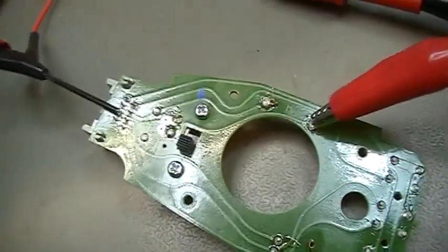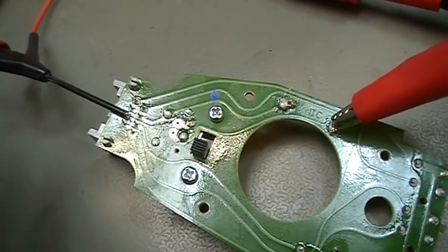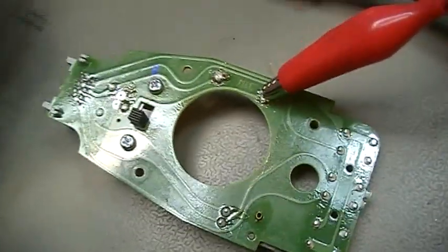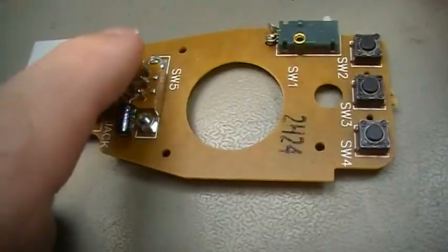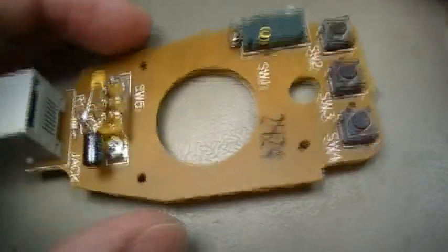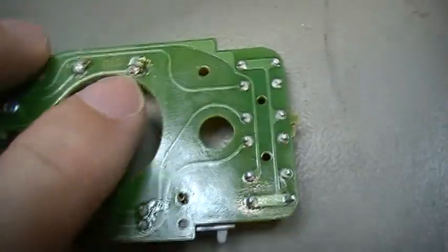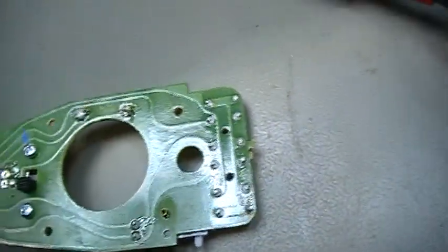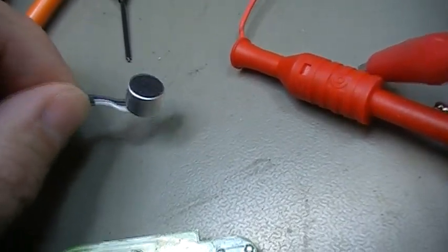This is, as I already said before, good for speaking on different modes, but it is also essential that these capacitors in either way will block the DC, which we need to supply to this point here, because as I already said, our electret capsules need 5 volt or whatever.